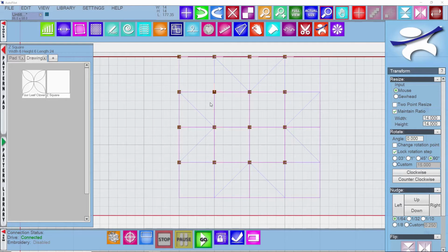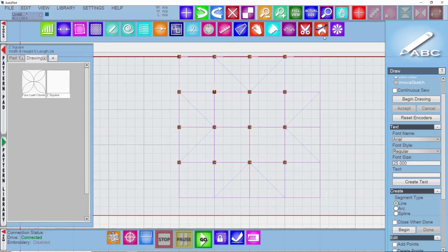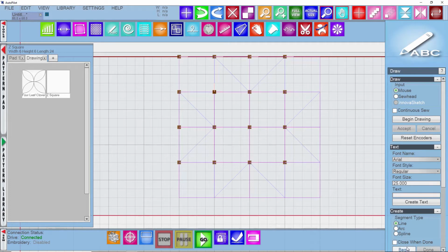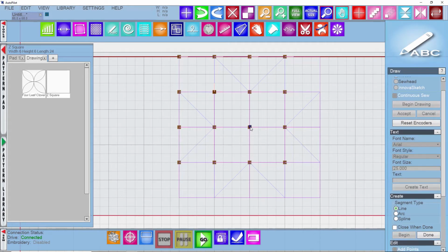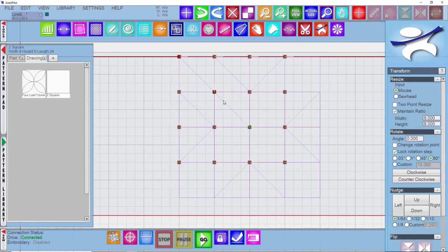Let's draw another design by dividing this into eighths. And so I'm going to go ahead and create a line to show where the diagonal would be. I still have my snap to grid on. Right click to stop that, and then I'm going to go back to transform, select that, lock it, and DQ it. And so we'll just draw 1/8 of the pattern and then replicate it.